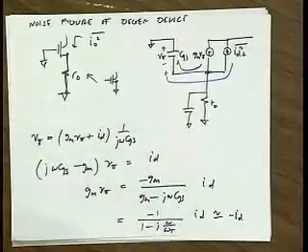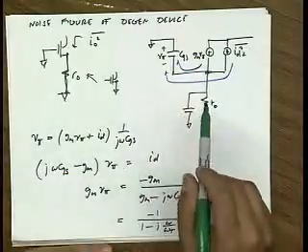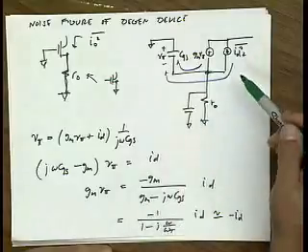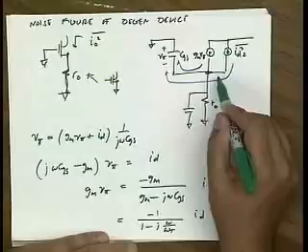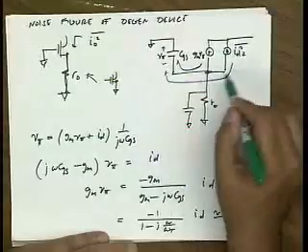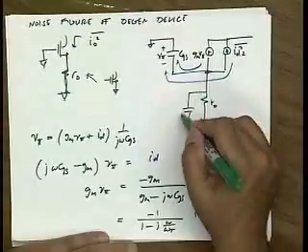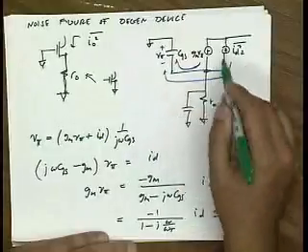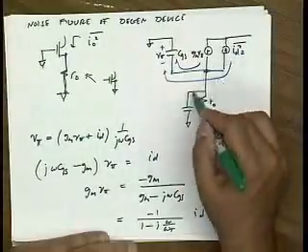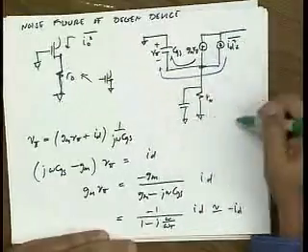Okay. There's a couple of interesting points about this perspective. This tells you that at really high frequencies, the amount of current that goes here is not necessarily all the current. Some of it will go through this capacitor, right? And as current goes through this capacitor, the amount of cancellation is reduced because this current will flow back into your load.